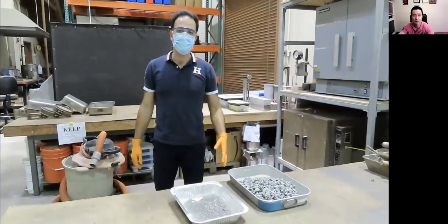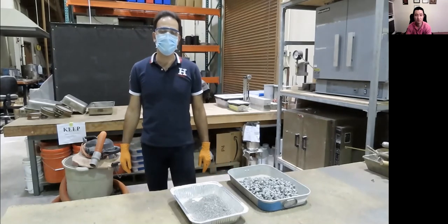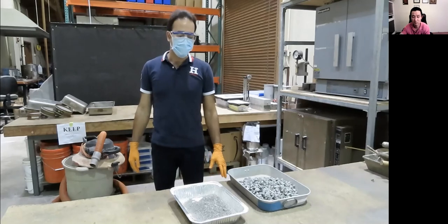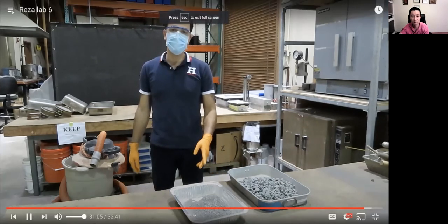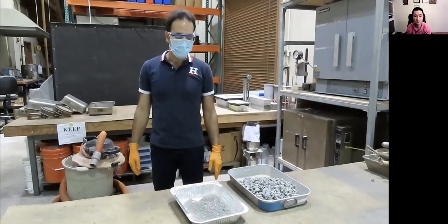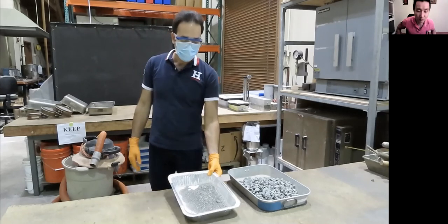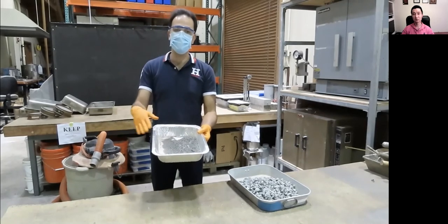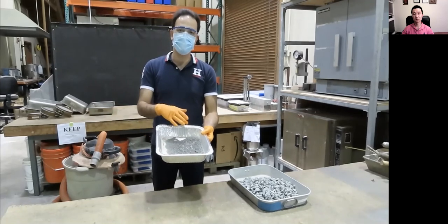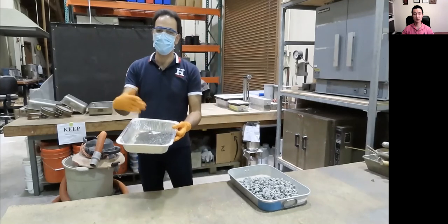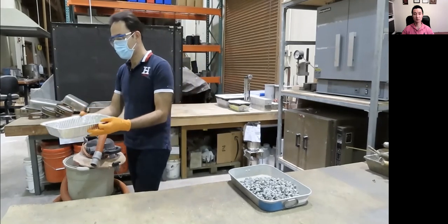Okay, you remember that we were here for the properties of the aggregate. We weighed our samples, for the fine aggregate and coarse aggregate in SSD condition. And today, I just took out my fine aggregate and coarse aggregate in oven dry condition out of the oven after 24 hours, and they're ready to be weighed. Just make sure that I put the whole thing, the aggregate and the container, on the scale. You have the numbers for the containers themselves, and you need to subtract it to make sure that you just have the weight of the aggregate in oven dry condition. So go ahead and weigh it.